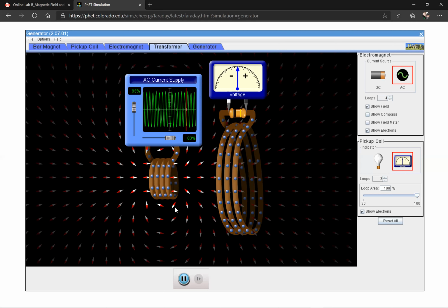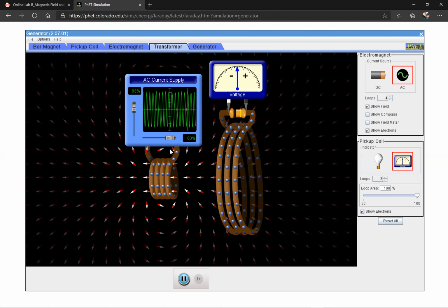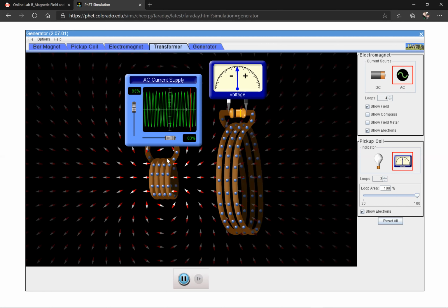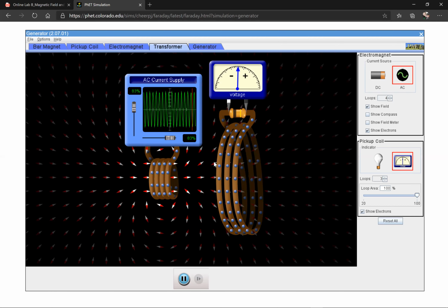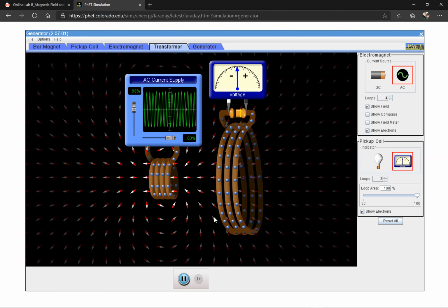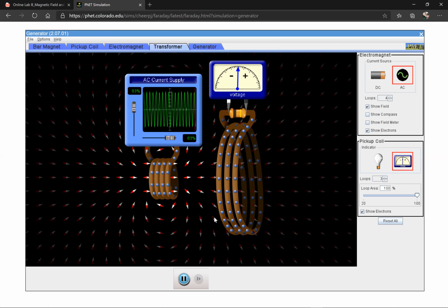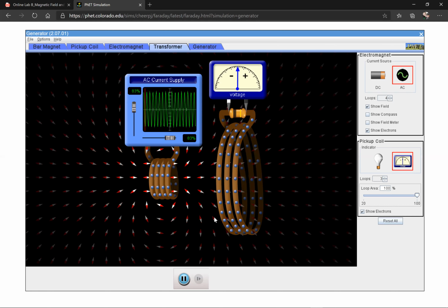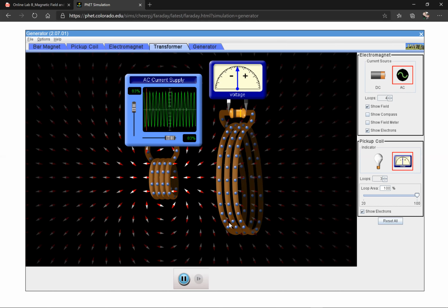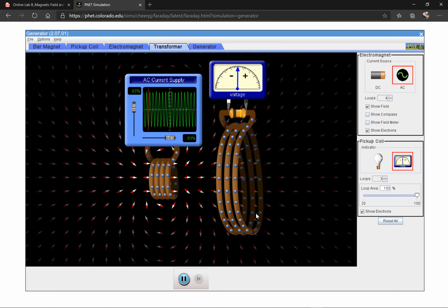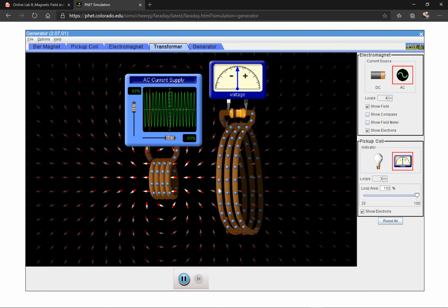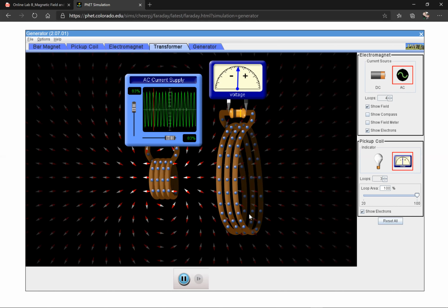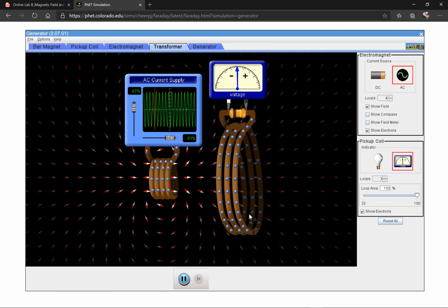Inside the pad, there's an electromagnet that is pretty strong, probably stronger than this one because we're not getting much voltage out here. But basically that electromagnet creates a changing magnetic field in the space just above the charger. Well, really in all space, but it dissipates pretty quickly. So the space just above the charger. And then the phone has a pickup coil, just like this, probably has a lot more loops in it because that'll get you a little bit more power out of it. But the phone has that pickup coil inside of it.